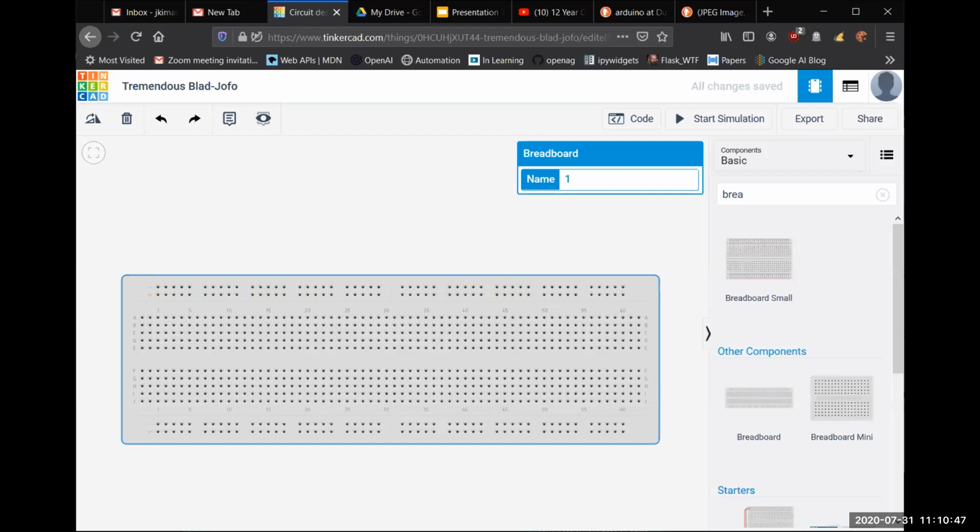And then for the numbers that are here at the top, they're just basically counting all these lines, all the way from number 1 until number 60. But these lines go this way. They connect this way, opposite to these ones here. Here you can actually see how they are connected. So if you connect to number 60 here at the top, that's 60A, then you connect the other connection to 60E. So everything should be 60. For instance, where we've done the buzzer on the breadboard, when you connect it to 60A, then the wire should go to 60E.